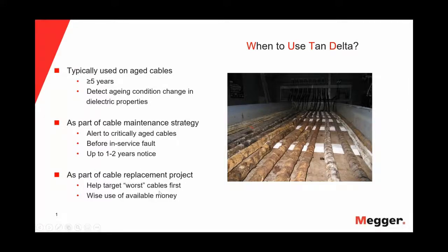It's also going to be used as part of a cable replacement project, and where this comes into play is that it's going to let you target the worst cables first and allow you to make the best and wisest choice with the available money, depending on how valued that asset is, on where you should spend your money first.